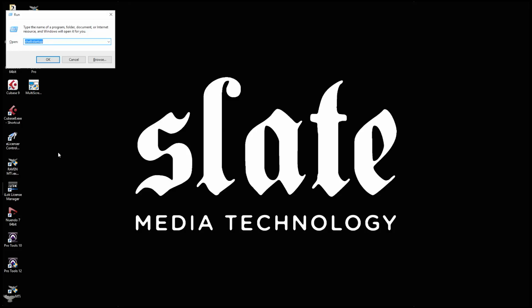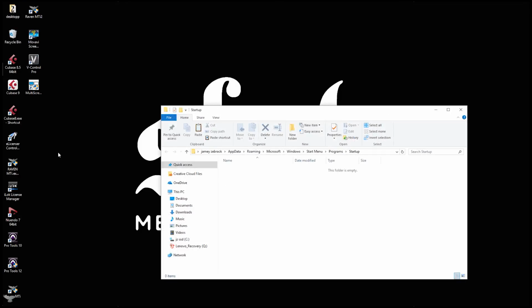Now, on the Run window, type shell:startup with no spaces and hit OK. Now, the Windows Startup folder will appear. Now, right-click within the folder and select Paste from the drop-down menu. This will paste the vControl Pro application to this folder and will instruct Windows to open vControl Pro on startup. Note: do not attempt to use a different version of vControl Pro as they will not work with the Raven.